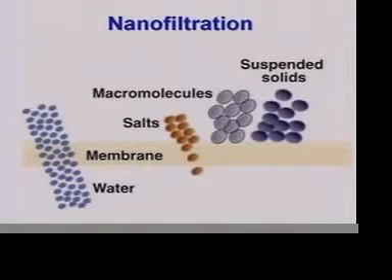Nanofiltration is a loose RO, and this has become a field in itself, in that the manufacturers are now making specifically nanofiltration membranes. In the early days, a nanofiltration membrane was a reverse osmosis membrane that failed quality control.